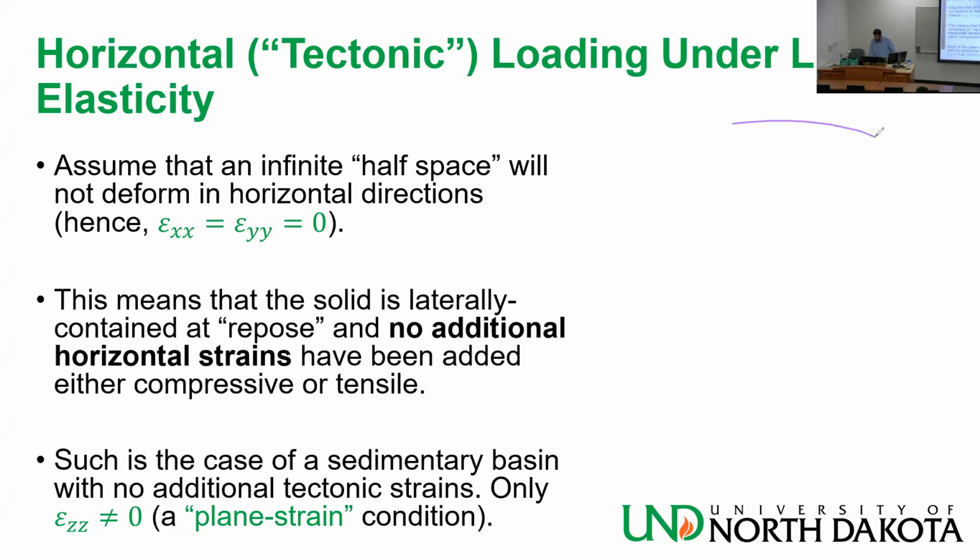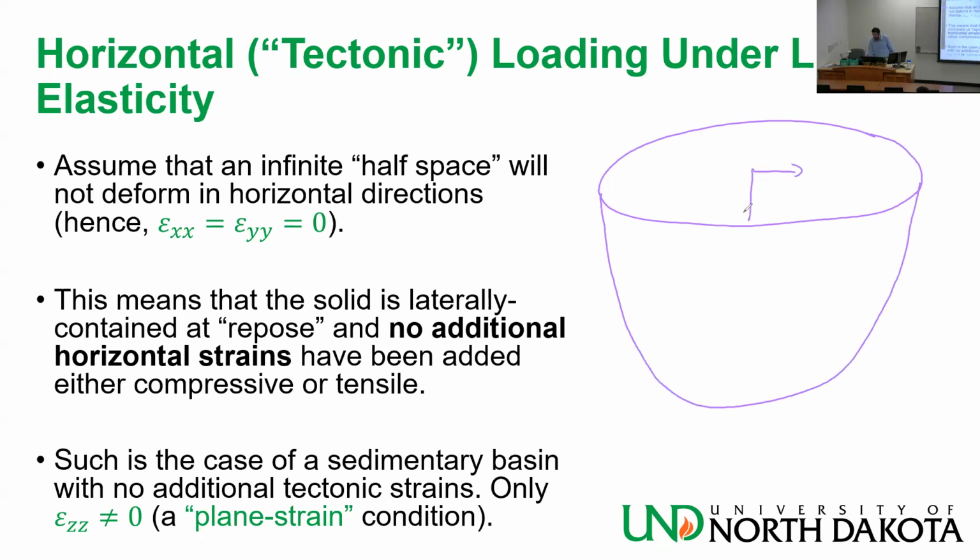Imagine a semisphere, gigantic radius, okay? Any radius, any increases in the X or Y direction basically generates strains that are equal to 0. Any increase you make in the X and Y direction, which is on the cross-section of that hemisphere, is basically infinitesimal. So effectively, my strain is 0. And then I only have strain in the Z direction, okay?